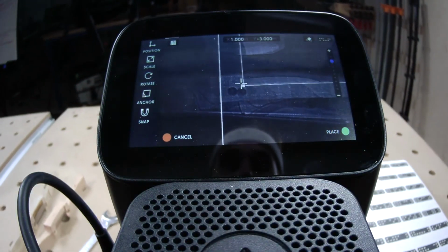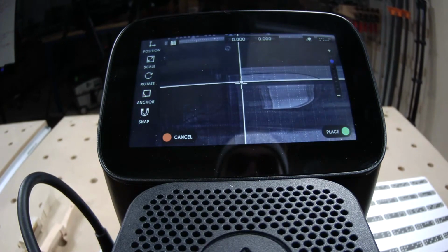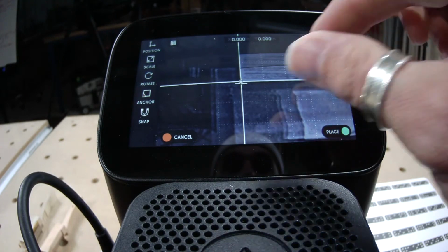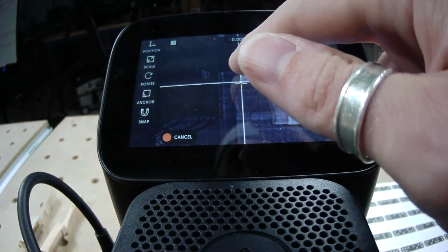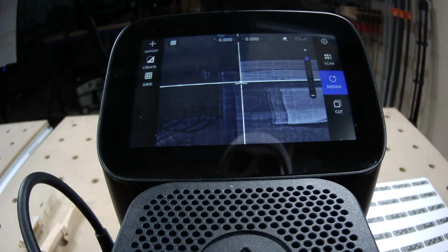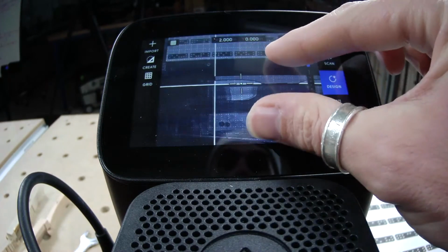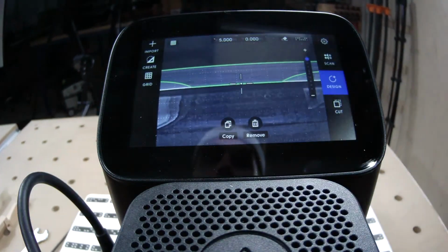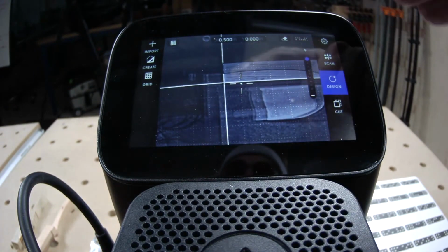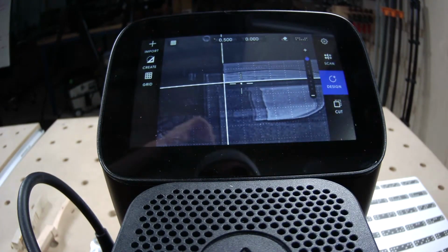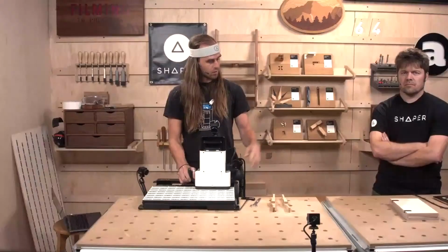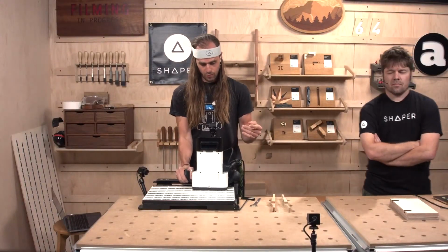And so what you're going to see is when I line this up with 0, 0 here, I could do it by moving the tool. I could do it by inputting position. I'm actually not placing that bottom of that curve on this piece. I'm actually including the stock dimensions in my file. So now that I place that, I have perfect alignment with this piece and with the design file without having to think about, do I grid the backside and then place off the top corner? You can just make your life a lot more simple by embedding these into the file themselves. And Sam is going to go over those in a few minutes. But let's get to cutting because we haven't done any cutting yet.